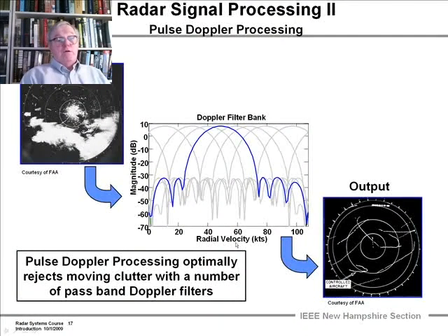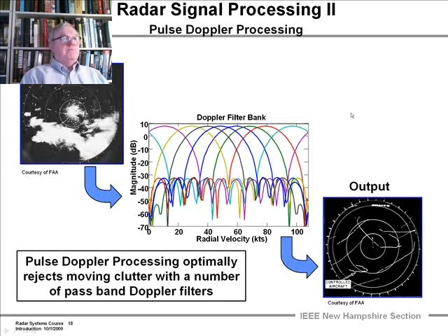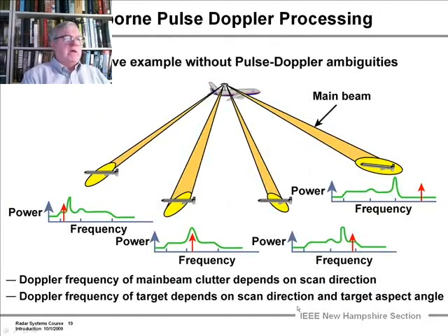And the ground clutter is all but disappeared. And this is a road leading away from the test site. You can see some detections from cars leaking through. This is just the time stamp on the output. Now, if you have a whole bank of the filters, this is what will be the output. What I showed you before was just one of the filters. So you get out of the 8 or 10 pulses, you get 8 or 10 outputs, and you look for where you get the threshold crossing in each one of them. And they're adaptively thresholded. We'll get on to all that in detail.